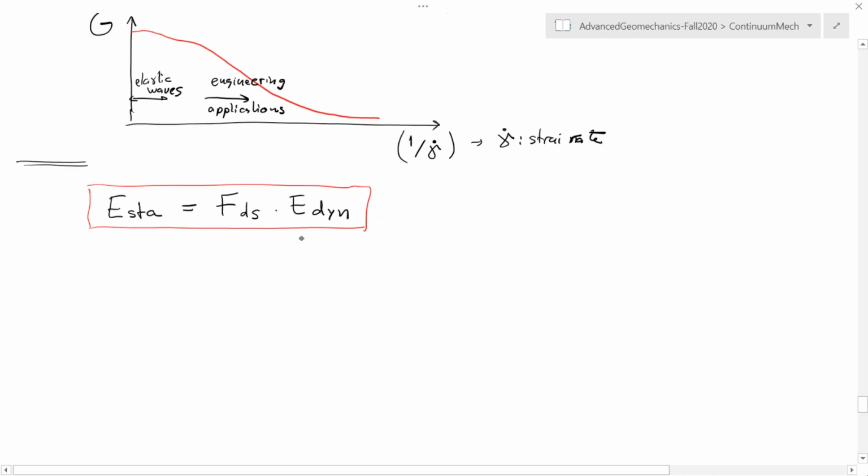And this dynamic Young modulus, then I'm going to obtain that, if I'm in the laboratory, from the ultrasonic elastic wave velocity, or the slowness, as you prefer, and the static Young modulus is going to be done through a triaxial test.